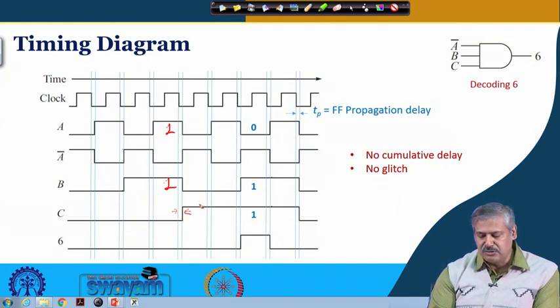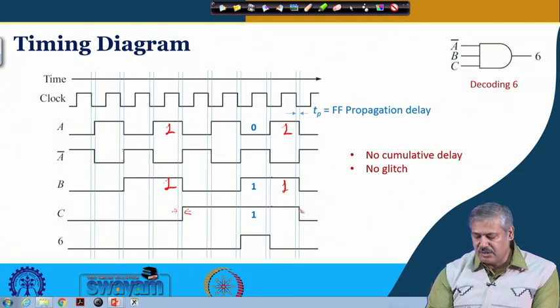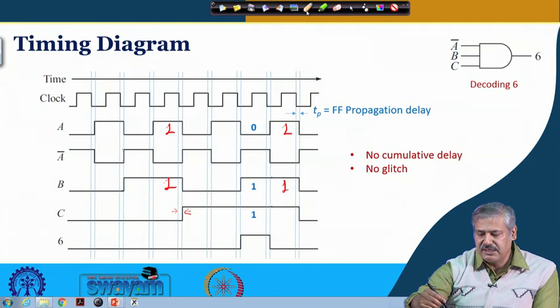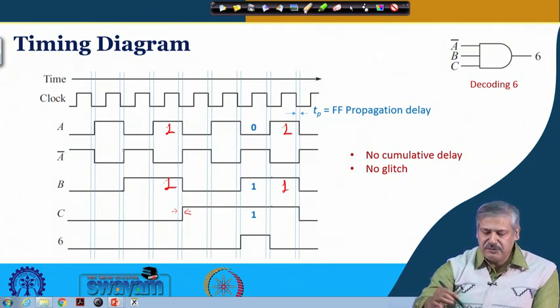So, this has become 0 to 1. Again it occurs in this place, when both of them are 1, it has gone from 1 to 0. So, that way you have got the timing diagram where the flip-flops are all changing at the same clock trigger and the values are available after 1 propagation delay, right. And because of which